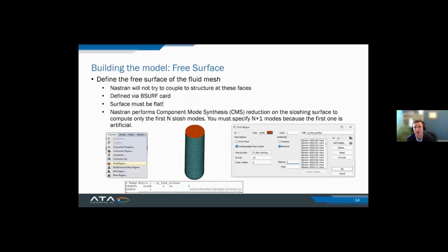Yeah, absolutely right. A CFD slosh analysis is obviously extremely expensive, and you can have multiple aspects of sloshing that cannot be computed with this, right? If you're a satellite in space at microgravity, and then you're starting your engines, and you want to see what your fluid does, obviously those type of simulations are completely out of the realm of anything that this method is able to do.